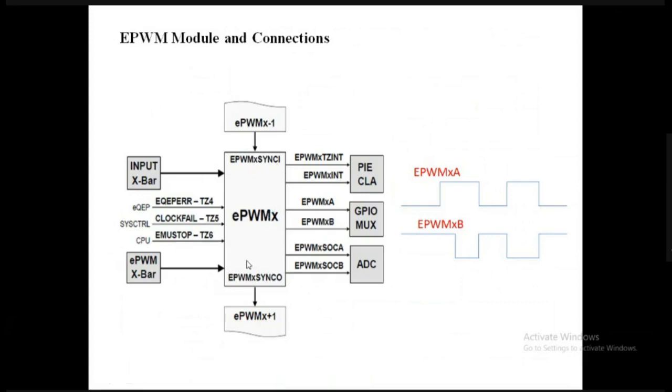Okay, so this EPWM module has its own synchronization logic, and when this EPWM module has certain submodules in it, like counters and timers that we'll talk about in a few minutes, those will also have their own synchronization logic. So we'll see how to synchronize those PWMs, as it is a main challenging task whenever you implement any PWM. However, very few instructions are required for that. But in order to understand that, it is important that you understand the basics of counters and timers.